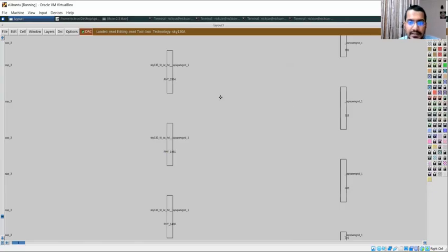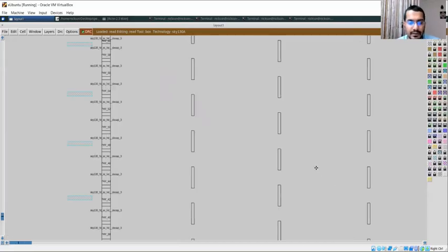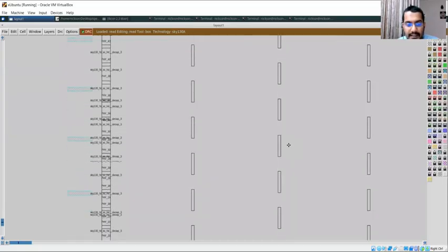And these tap cells, you can see they are diagonally equidistant. This tap cell and this tap cell are diagonally equidistant. So this value has also been set. If you refer to the README, you can see which switch is used for the tap cell distance. And to bring to your consideration, this is floor plan. As I had mentioned before, floor plan does not take into consideration the placement of standard cells. But standard cells are present here.